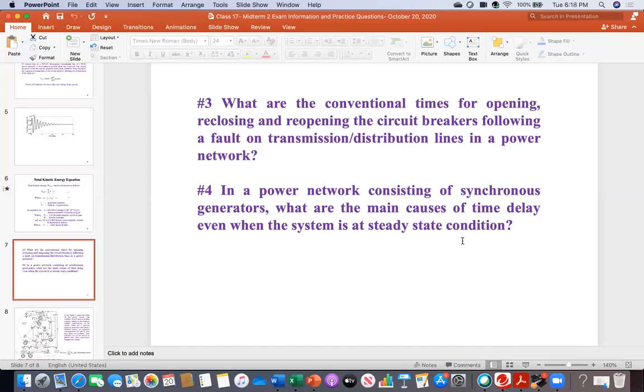Therefore, once there is a transient situation, transient stability or voltage stability or load change, something happens, and you want to initiate some controller, whatever it is, braking resistor or STATCOM, SVC or any energy storage device, then those devices require some input for their functioning, for their control operation. And at that time, the additional delay will come in the process.